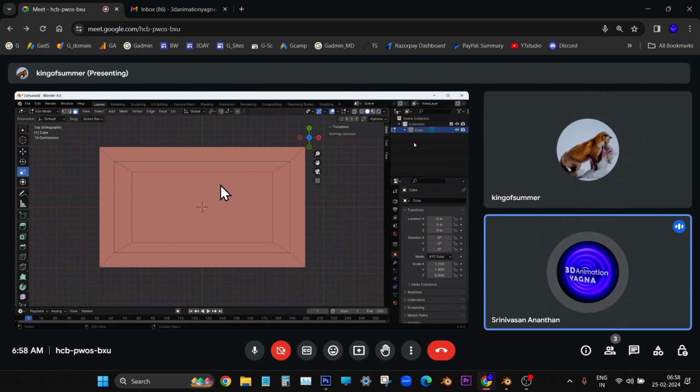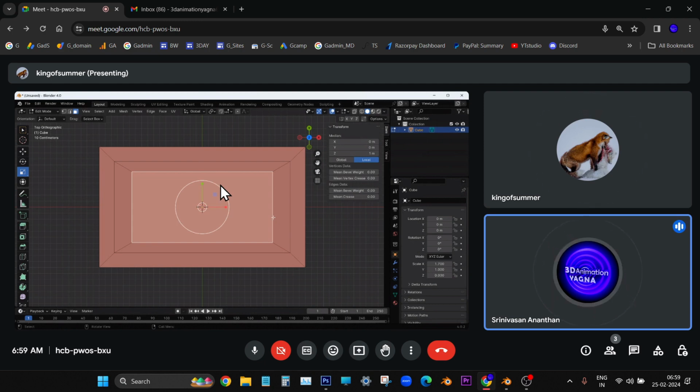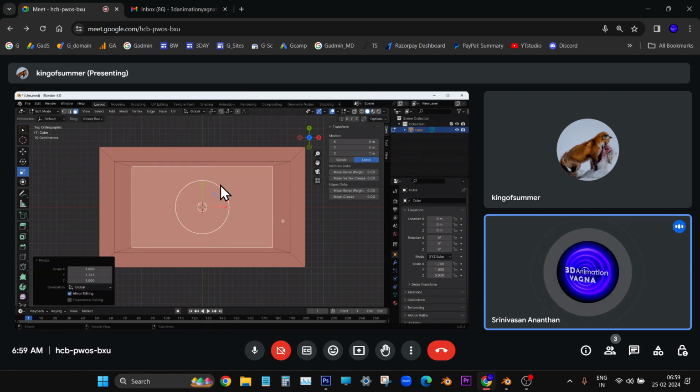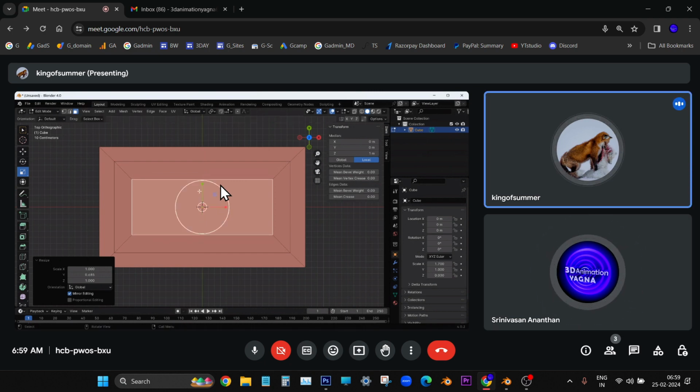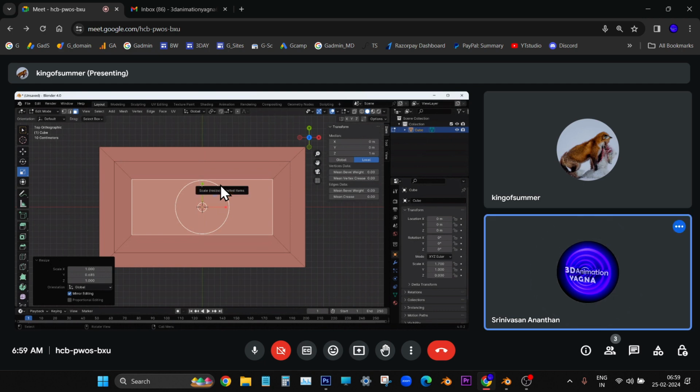No, no. Select the face and then try to move. Now you try to scale it in the y-axis. Yeah, this is correct. So scale it down in the y-axis. Slowly, slowly. Little more, bit. Yeah, enough. Little up, little up. Enough. Oh no. That is the sides should be same. The size of the side regions and the top region should be same. Little scale it down.